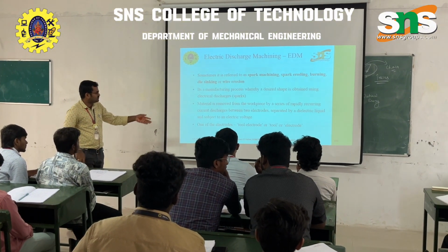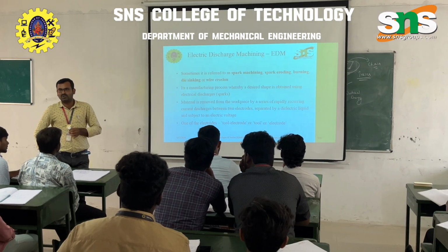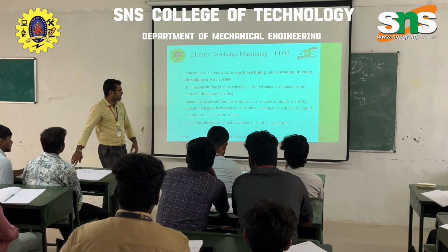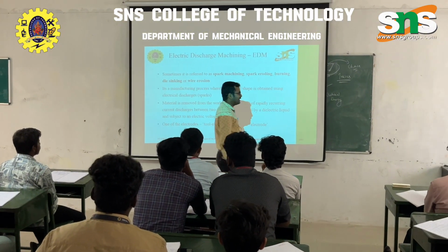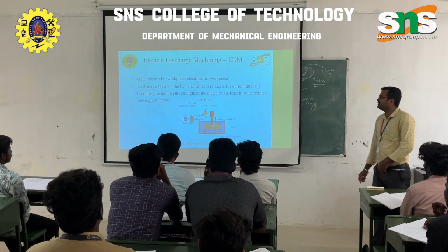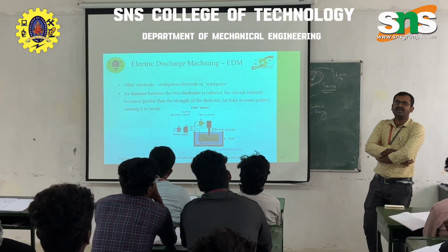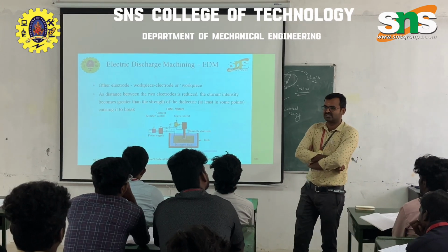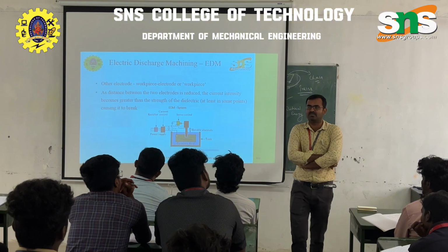Okay. Then last, here we have two electrodes. One is the tool electrode and the other is the workpiece or work electrode. One electrode is known as the tool electrode, or generally just the electrode. The other electrode is the workpiece electrode, or workpiece. Generally the distance between the tool and workpiece is maintained by using the servo control system. It may be around 0.05 to 0.10 mm gap.